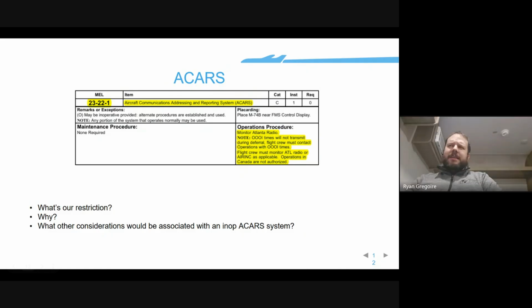Yeah, if you saw something that you thought would or had the potential for definitely leading to information needing to be relayed to the crew ahead of time, that would definitely be a situation where it would probably be good to reach out to your pilots before the flight and say, hey, just so we're on the same page, with your ACARS inoperative, with this weather en route, I may need to reach out to you if there's any shifts in where the weather is and changes that I think need to be made to your flight plan.